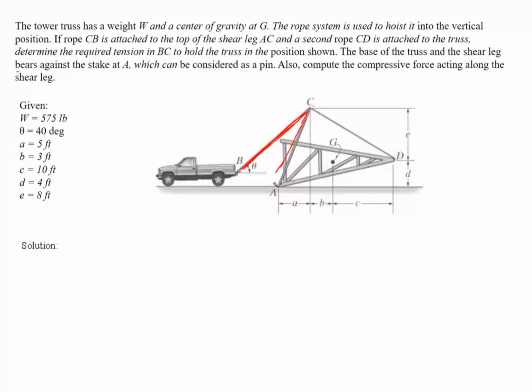So BC is outside the system. So let's draw the free body diagram of the whole structure, this one. Let's draw the free body diagram of this structure. So what we'll have. So it's pin connected here. So you do know if it's pin connected, it can rotate but cannot move in XY. We've got active weight downward. And we've got a pull force here.